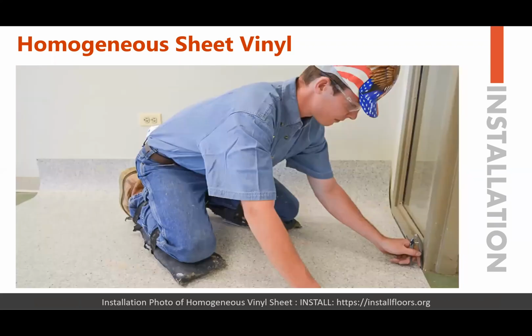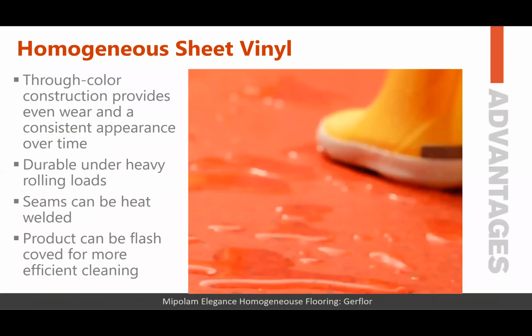You can also see the level of detail. So when you're really cutting and verifying how the installation is going to occur, homogeneous sheet vinyl, as on any sheet, would really require a lot of attention to detail and making sure that it's installed correctly. Various advantages for homogeneous: through color construction provides even wear and a consistent appearance over time. It is very durable under heavy rolling loads, and seams can be heat welded. The product can be flash coved for more efficient cleaning, which is consistent with other sheet products as well.